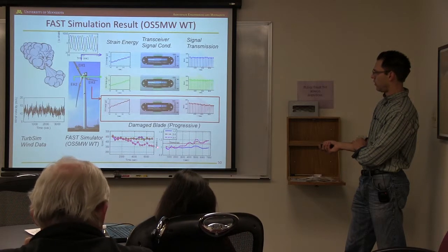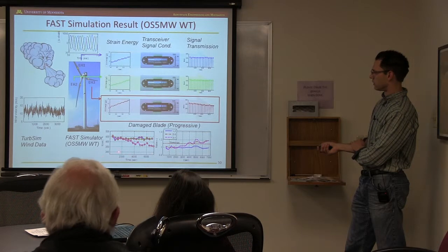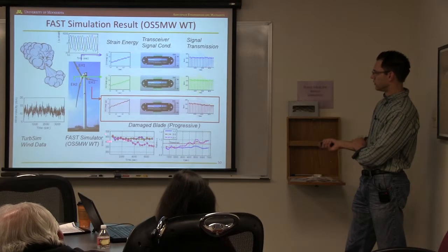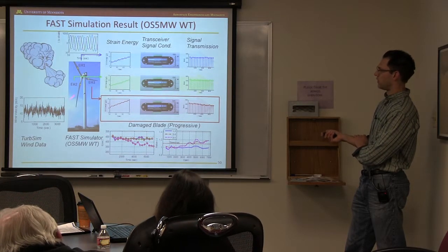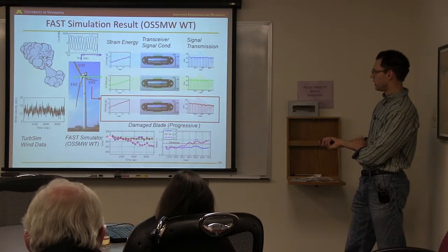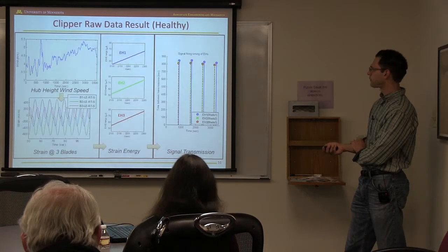So this is supposed to represent time between pulses as a function of the time that you're receiving the pulses. So 2 of the blades, you're receiving pulses at about the same time, but there's random stuff going on here. The blades are all getting slightly different wind loadings and so on. So there's some variability, but over some amount of time, hopefully you can detect these differences.